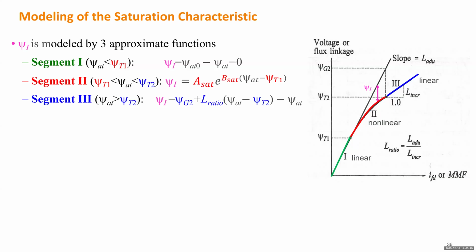For all the parameters I colored in red or blue, which need to have some values in the model, if you want to use this model, you need to look for those values. Then you can draw this function. Once you draw it compared to the unsaturated curve, you can calculate this ratio, and multiply the unsaturated inductance by this ratio, and that will give you the accurate inductance.